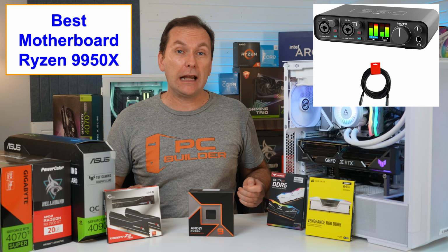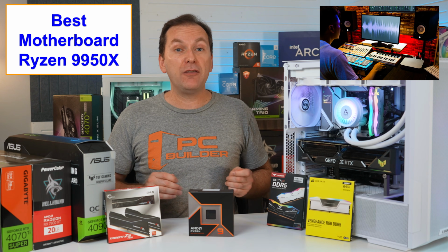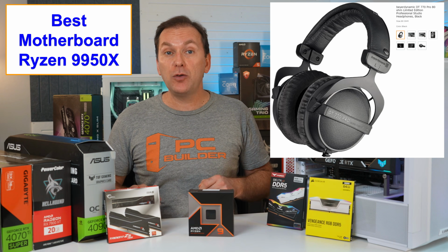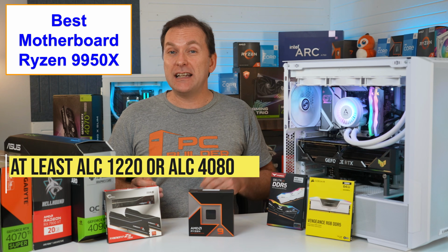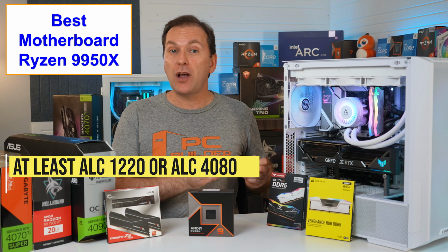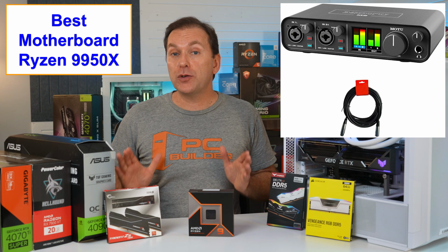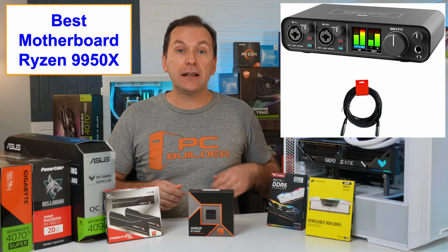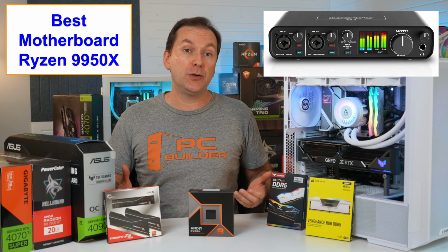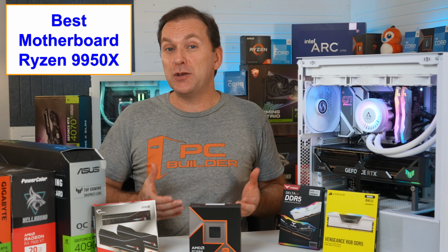In terms of the audio, if you do not have an external digital to analog converter, or DAC for short, and you intend to plug in analog headphones into your PC, particularly for those sound and video editors who are working with high impedance headphones like the DT770 Pros that we use, you're going to want to get at least an ALC 1220 or ALC 4080 audio codec with support for those high impedance headphones and good quality speakers called studio monitors. You can, of course, always upgrade to an external DAC, like the Motu M2 for $199 or M4 for $270 in the future. When it comes to external audio equipment, of course, I'm not necessarily an expert, so feel free to do some additional research.